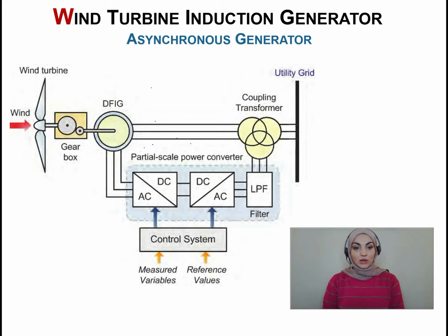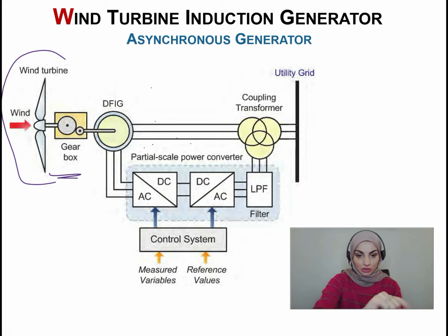So, in the context of wind turbines, the mechanical energy is obtained by capturing the energy in the wind with a turbine rotor, and in some turbines, converting that high torque and low speed into low torque and higher speed using a gearbox over here. Doubly fed electrical generators run at speeds slightly above or below their natural synchronous speed, mostly above. This is actually useful for large variable speed wind turbines because the wind speed can change suddenly.